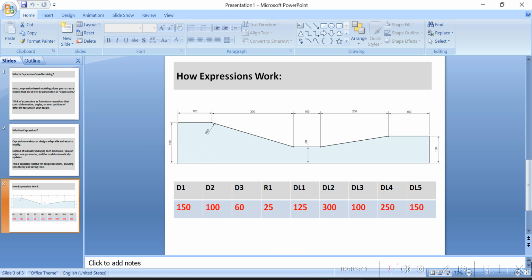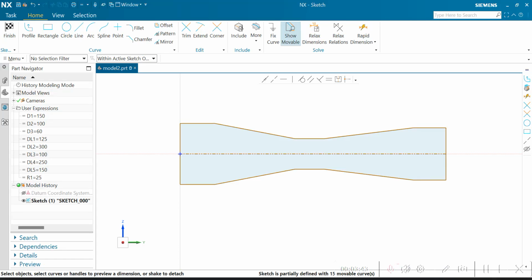But with the future in mind, we need to create the full half-cut section of the revolve body, because you get some difficulties when giving diameter values by half. So it is better to create the full half section, the revolve half section. Okay, let's start.